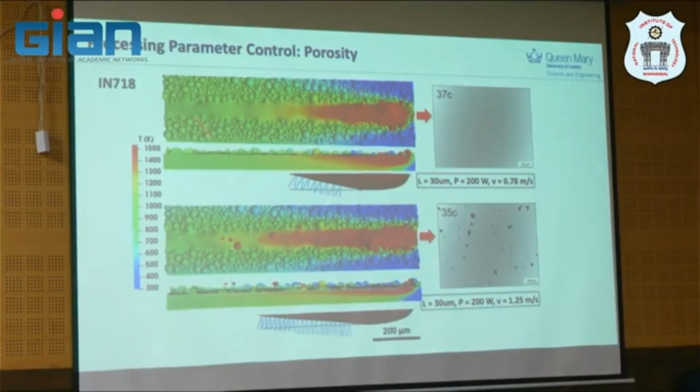If you do it properly, you will see that different inclinations may suggest different grain or dendritic formation, whether it's dendrite, planar growth or cellular growth, because of the characteristic length scale. The microstructure during additive is mostly non-equilibrium. It will be a cellular structure, not quite dendrite, a very small, fine dendrite. We'll say more on that later.